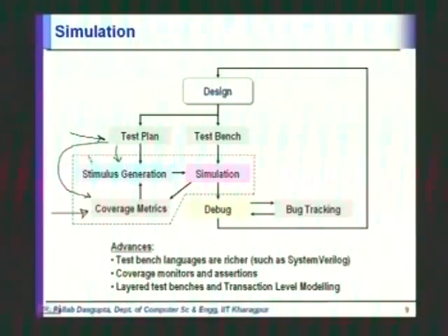So you can express that again as a property here, and they are called cover properties, right? And just like any other coverage metric, at the end of the simulation you produce a coverage report saying that these properties were checked, and these properties were not checked because their conditions never happened. And for simulation coverage metrics like code coverage, transition coverage, etc., a separate report is produced.